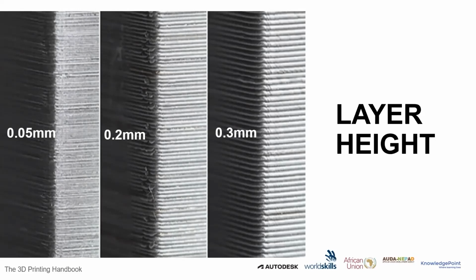But when the layer height is increased, the part has rougher details. You can see the surfaces get rougher, but it really helps you reduce the printing time.